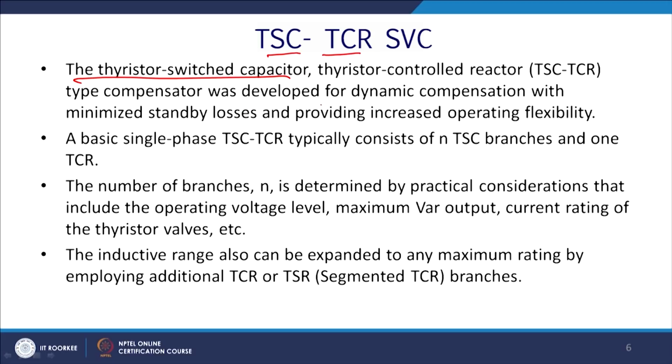Actually, this compensator was developed for dynamic response with minimized standby losses, providing increased operating reliability, because you can also frequently turn on and turn off this TCR, and apart from that you have the TSC. That also can be turned on very frequently.